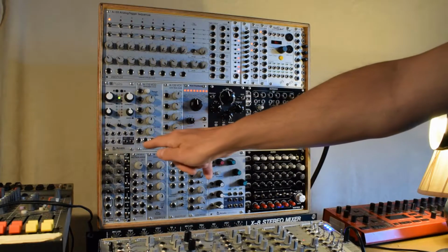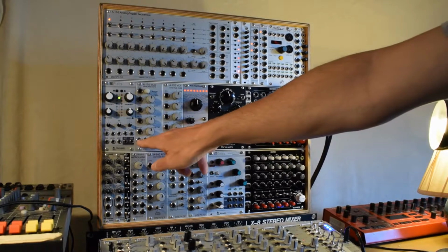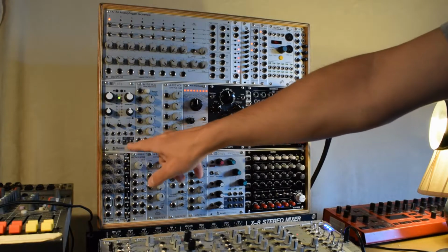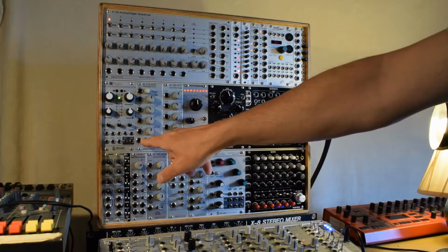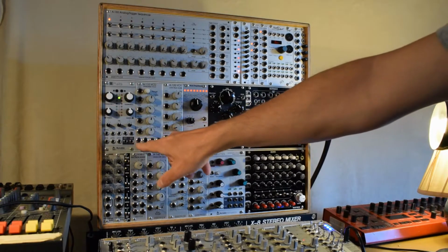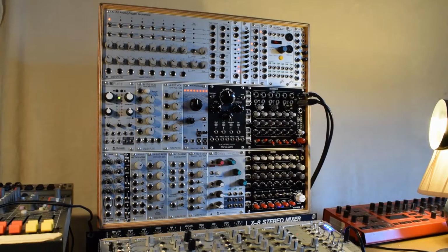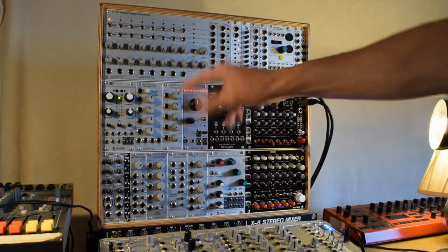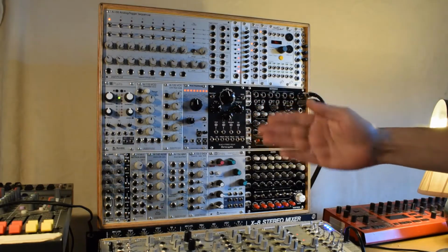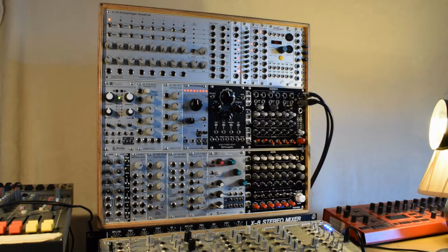This one produces 4 different waveforms which come out of these 4 sockets at the bottom here. I don't think you'll be able to see it on the camera, but basically they are a sawtooth wave, a square wave, a triangle wave and a sine wave. They're very basic varying voltages that go up and down in a repeated pattern, at such a rate that when you plug them into a speaker, the speaker moves at the same rate that the voltage is varying, and that produces a note or a tone.